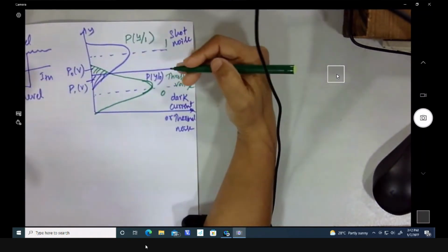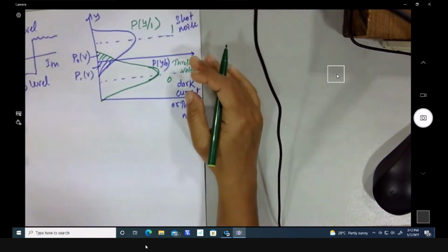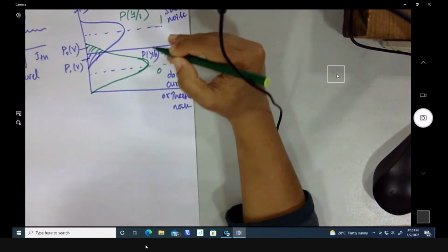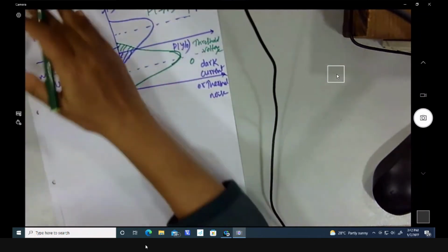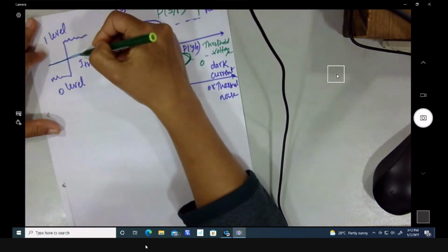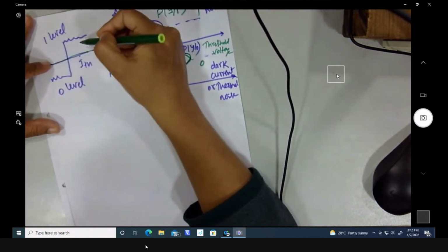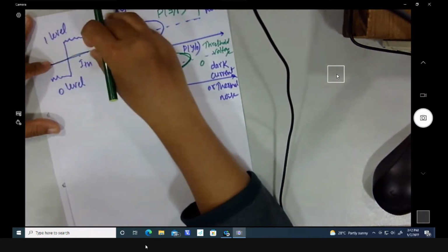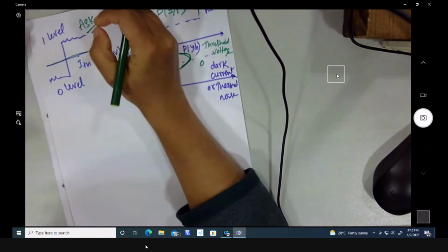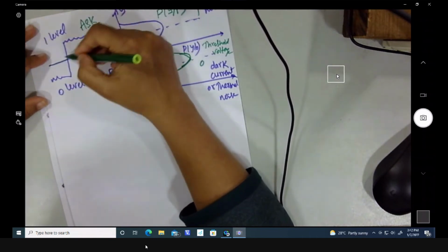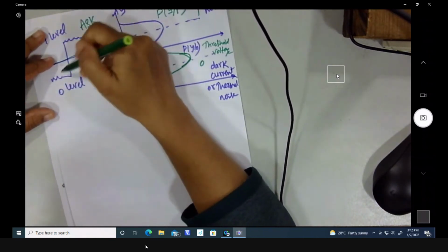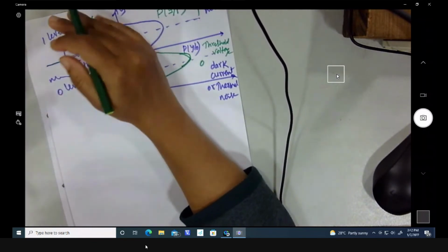So these are the density functions that I have written. We can take a threshold voltage or threshold current. So this is the threshold current that I have considered. And the signal level above this threshold current, we are going to consider as 1. The modulation will be amplitude shift keying for the digital signal. So the optical signal will be present for the 1 level and the optical signal will be absent for the 0 level at the 0 bit transmission.